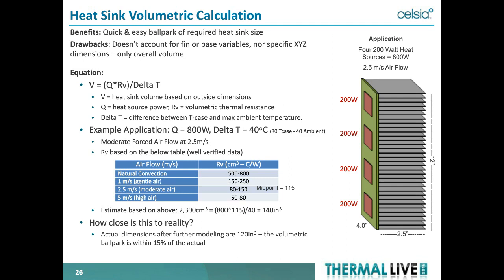So if you do the quick calculation, it says, hey, I need 2,300 square centimeters, convert that to cubic inches, I need 140 cubic inches. So you can get an answer in a couple minutes as to how much space you think you're going to need. How close is this to reality? Well, the final design for this particular application was 120 cubic inches. So the good thing is it over-predicted the space you needed a little, but it's within 15% of what the real solution turned out to be. That's close enough for that phase of the design.